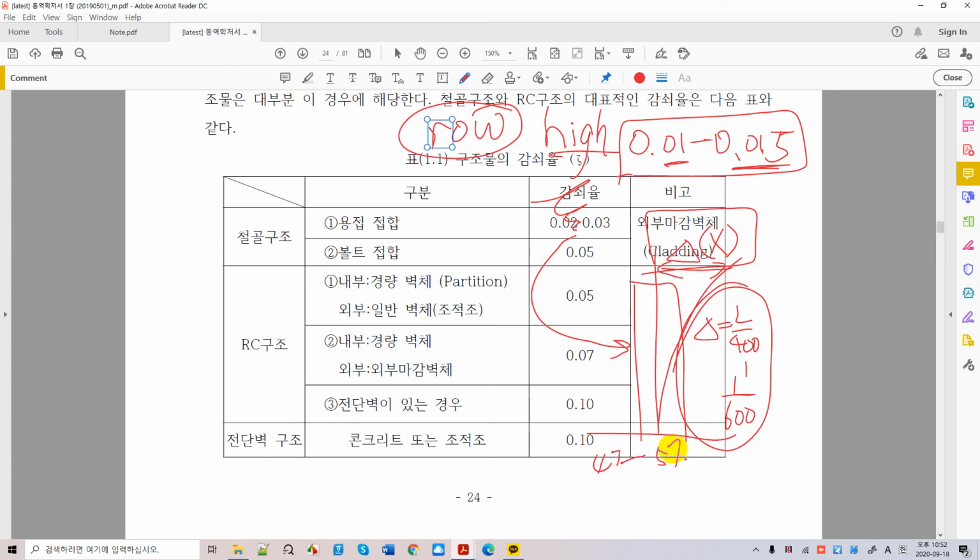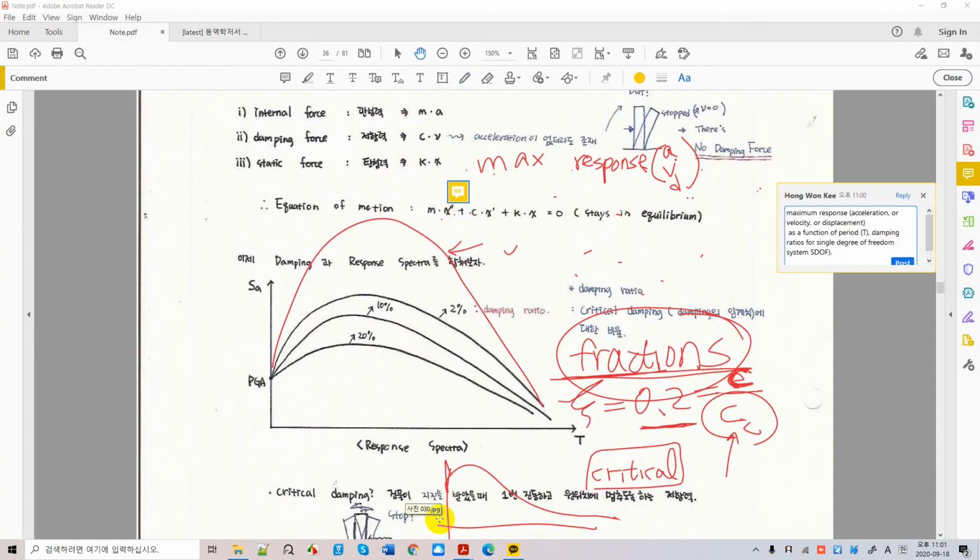Right? And don't forget, you just have to put the 1% to 1.5% of natural damping, and you can increase it by putting in artificial damping. Okay, I'm not going to repeat anymore. I hope this is enough to explain what damping ratio can do for you. Okay, let's go back to the response spectrum. And now you don't want to forget about the damping ratio.